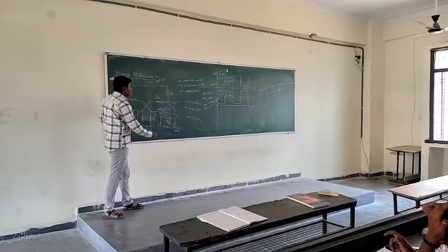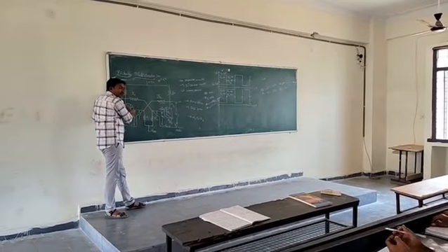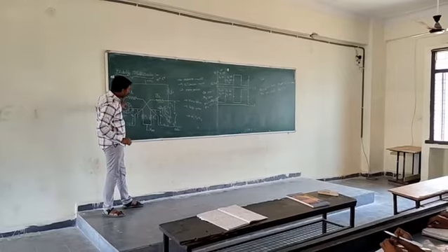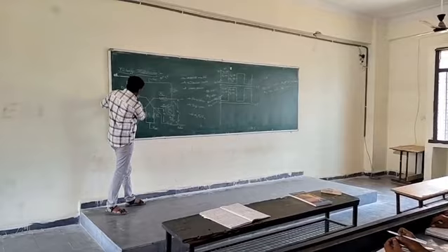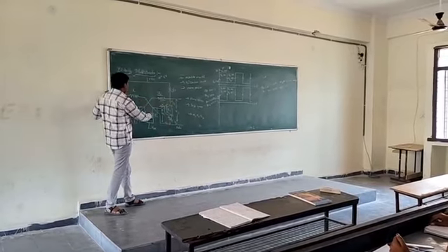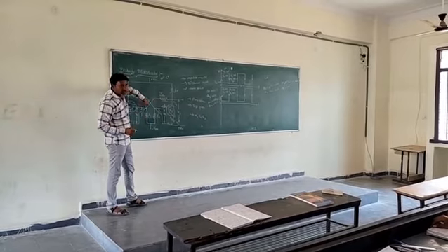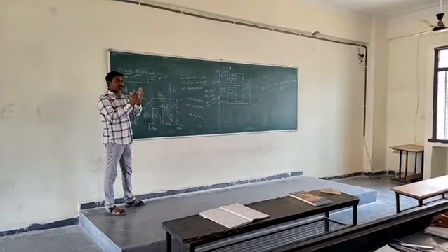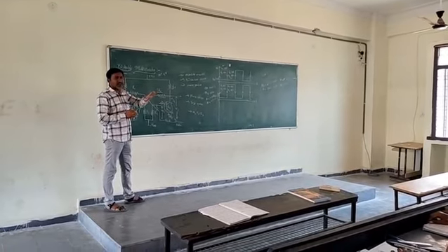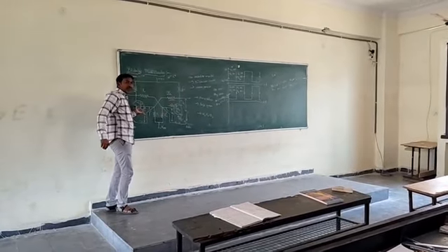Through the resistor it goes to the base of transistor Q1. Then the Q1 collector is coupled through the R1 resistor and connected to the base of Q2. The output of the first transistor is connected as the input terminal of the second transistor, and the second transistor output is connected as the input terminal of the first transistor.